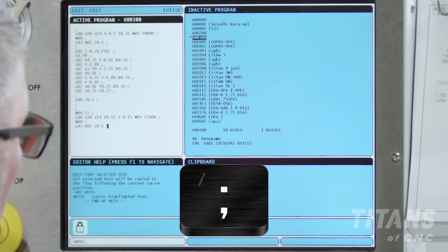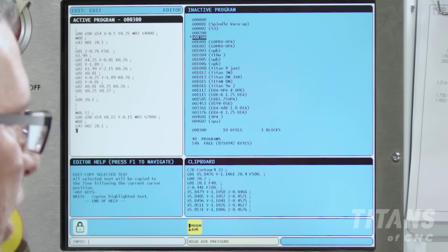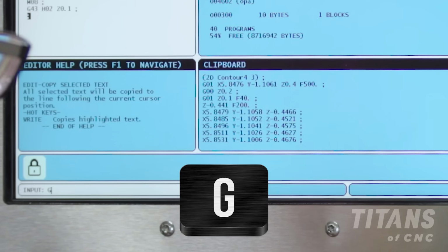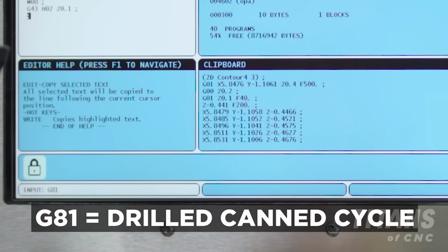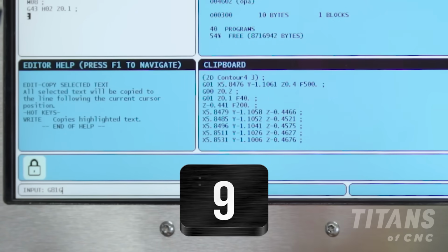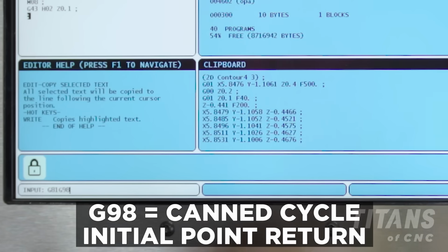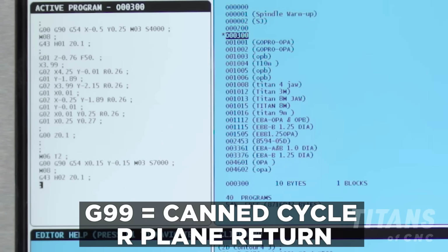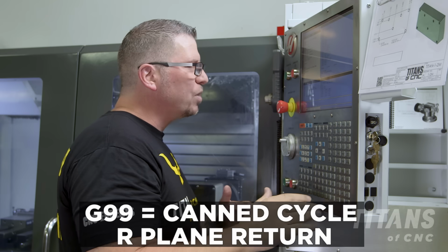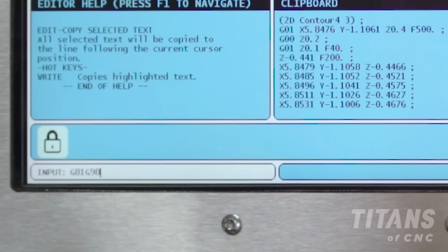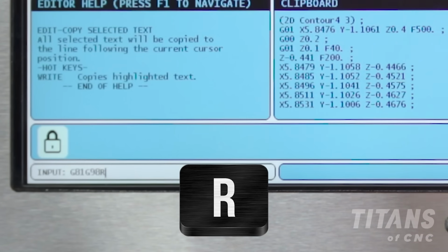All right? So now I'm gonna show you something different than milling. This is a can cycle for a drill program. So we're gonna go G81, drill with no peck, right? Just come down, boom, all right? G98, when the tool raises back up, it would go to our initial plane, which would be on the G43 line. If I had a G99, it would go to our rapid plane. In this case, they're pretty much both the same because we went Z.1. So next one is R, which is our rapid plane.